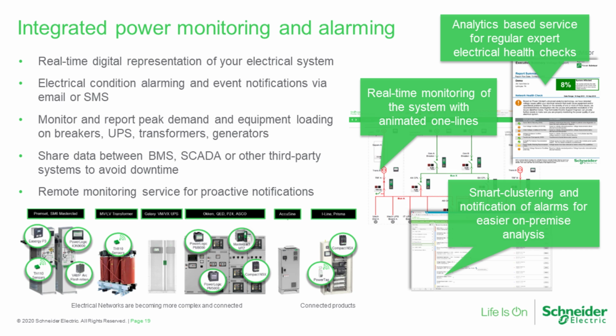So what can we do? Well, we can bring in power monitoring points, critical points like condition alarming, maybe measurement of peak demand, loading, things like that. You can bring the data from the IoTs so that it's visible from your management system, whether you have a dedicated power management system or whether you want to take that data and integrate it with the building system. That's an implementation detail.